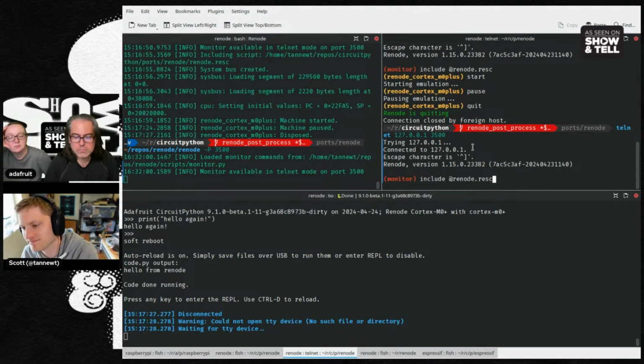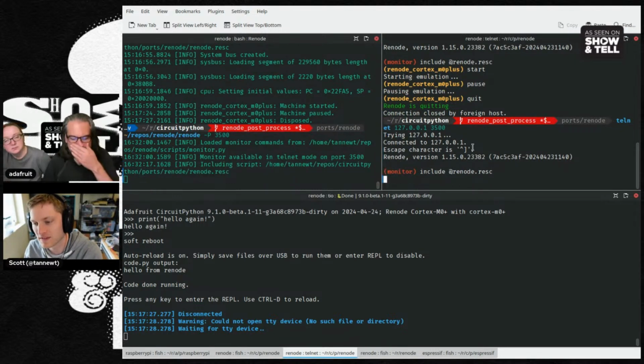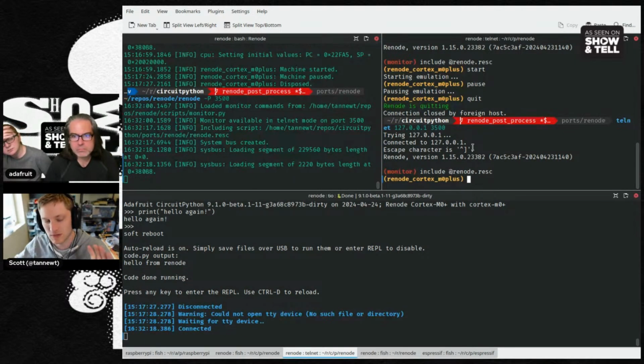This is a Renode script file. That sets up what sort of CPU and loads the code into the emulator. It also loads a CircuitPy file system that make generates for me based on a directory.